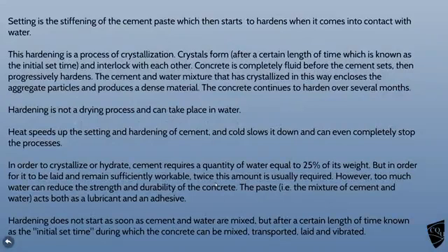Setting. Don't confuse it with hardening. Setting is basically just the stiffening of the cement paste in the concrete. It starts off when it comes into contact with water. So as soon as you add water to your cement, it's going to start stiffening. Hardening is a process of crystallisation. Crystals form after initial time, and they actually interlock together. Concrete is completely fluid before it starts to set, and it progressively hardens.